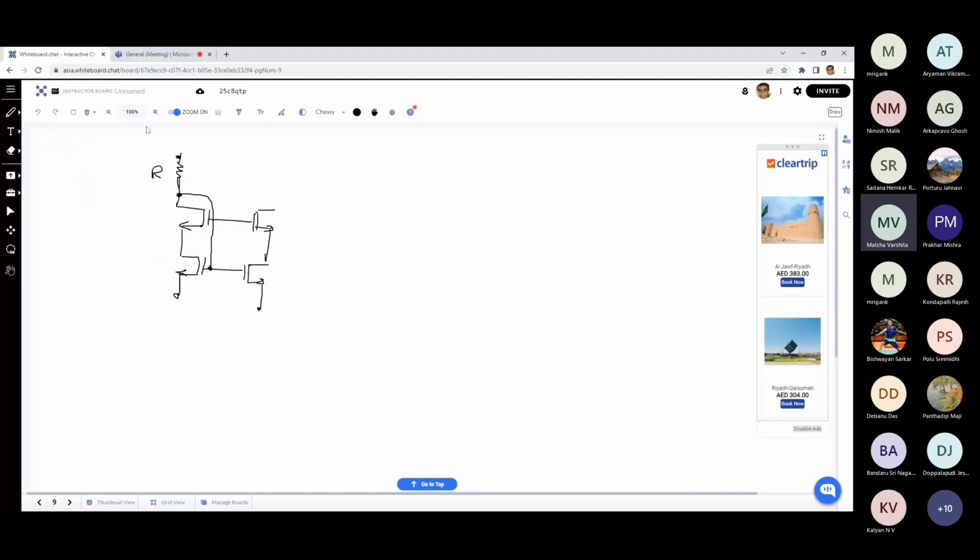This is the current source coming from VDD. So this is your IREF. We have not discussed how to generate IREF. One of the simplest things that we have seen is you just put a resistor and a MOSFET that generates IREF. But we will discuss more accurate methods, and we also have a dedicated chapter just on reference generation. You can look at it.